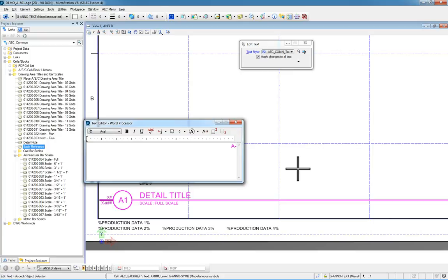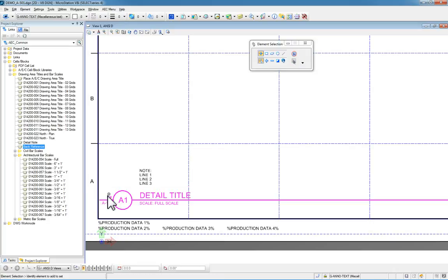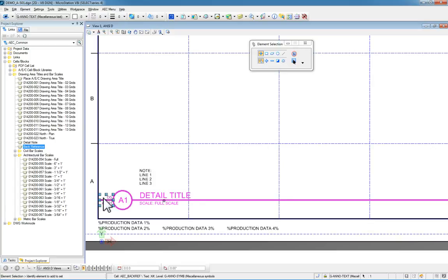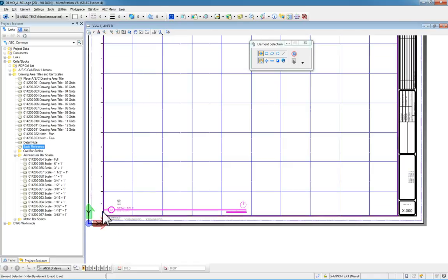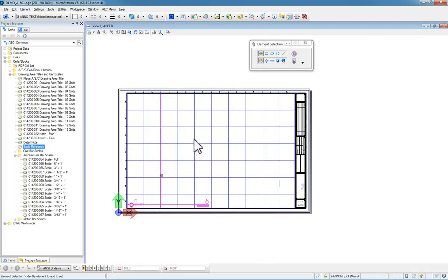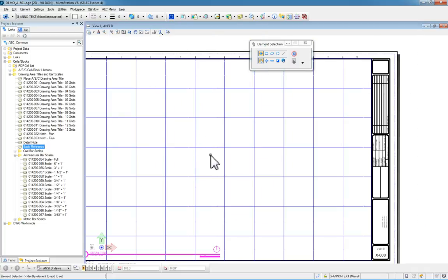So let's say this was on A101 that it was cut on, and then what grid location you would find that section cut or detail or whatever that back reference would point to. So maybe that one would be found in maybe like D5. And that would be a proper back reference, because that would make it easy for the person looking for the back reference to be able to find that grid location where it would be located.